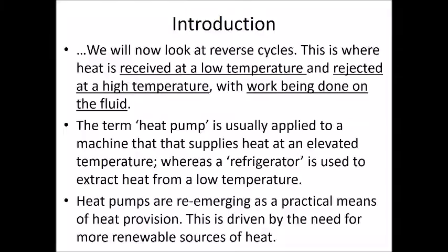I'm going to have to store all that energy up and then discharge it suddenly and get really impractical performance, whereas a heat pump is something where you can take a small quantity of heat and just keep it ticking over, just keep slowly upgrading. And also I'm getting more than I put in, aren't I? So if I'm taking heat from one reservoir and pumping it into another, the amount of electrical energy I need will be smaller than the amount of heat that I can usually realistically pump. And that's coefficient of performance, which we're going to learn about later.